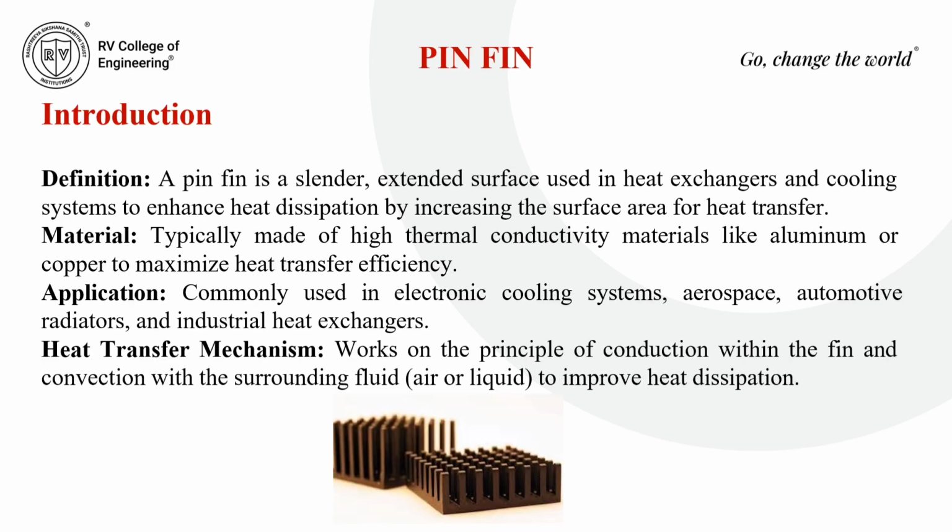Pin fins are extended surfaces which are used in heat exchangers and cooling systems in order to enhance heat dissipation. By increasing the surface area, it will increase the overall heat transfer rate. These are mainly made of high thermal conductivity materials like aluminum or copper, so that will maximize the heat transfer efficiency. These types of pin fins are used in a wide variety of applications, majorly in electronic cooling systems, aerospace industries, and automotive radiators in order to cool the coolant oil, and in some industrial heat exchangers as well. It works on the principle of both conduction and convection.